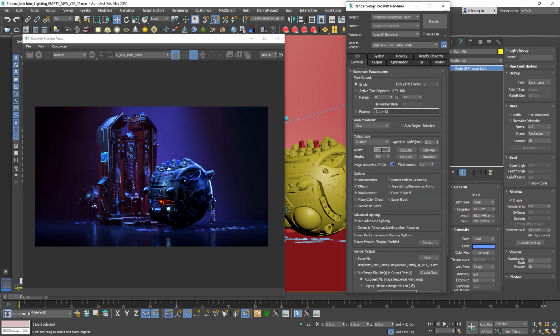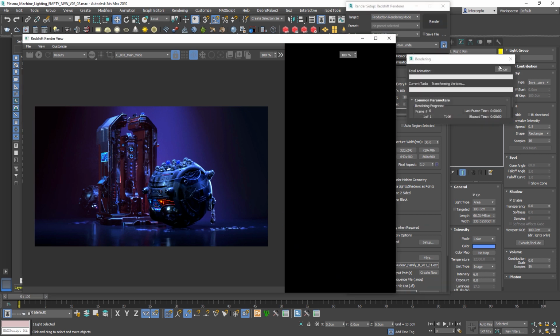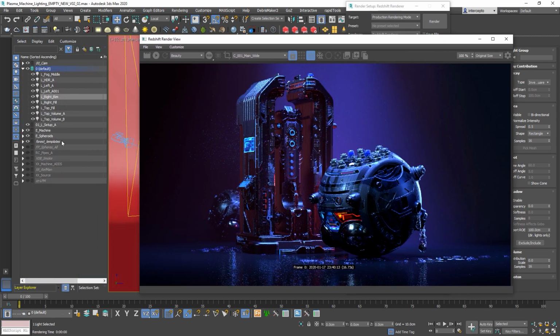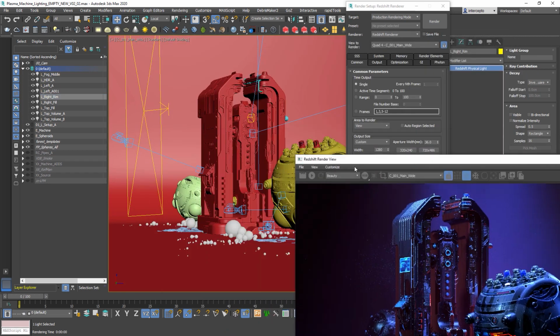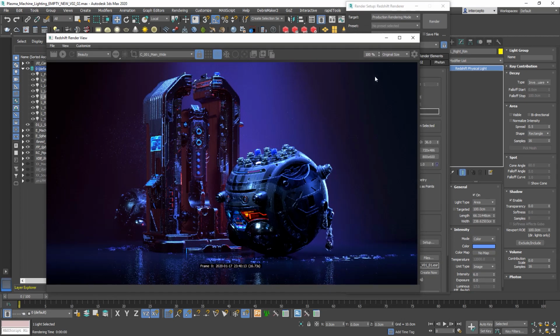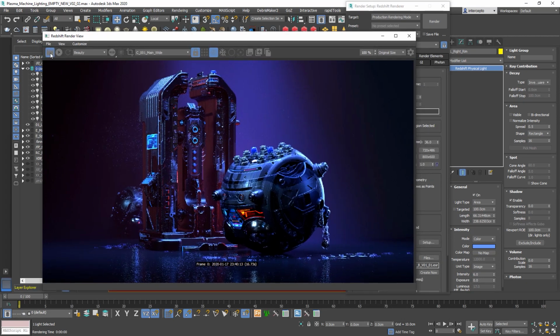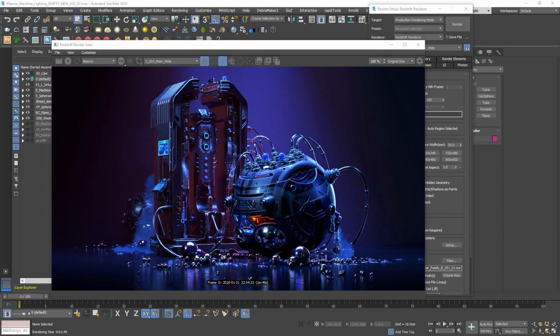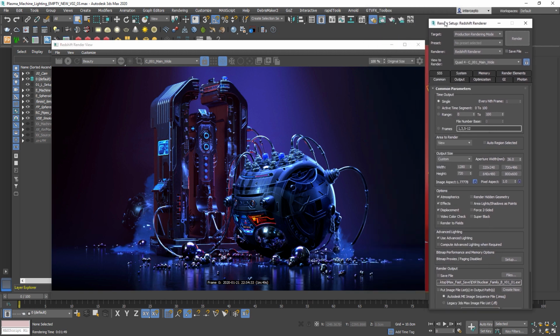And then go back to common, let's increase resolution a little bit and click final render. Actually, before doing a final render, let's turn on all the spheres in the foreground, and I'll turn on pipes, and I'll turn on VDB smoke, so we have everything in the scene. And let's do render again, and I'll just pause this and wait for it to be done. So this is a final render. It took only 1 minute and 50 seconds to render this image, although it's relatively small resolution.